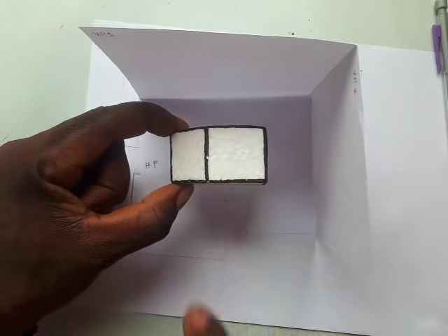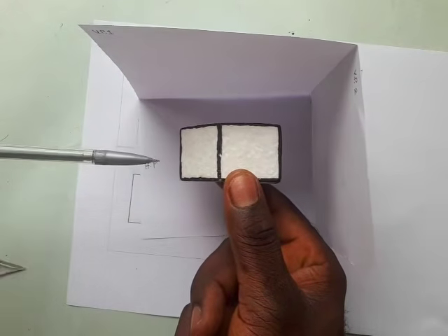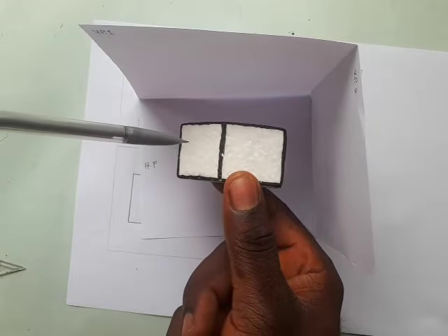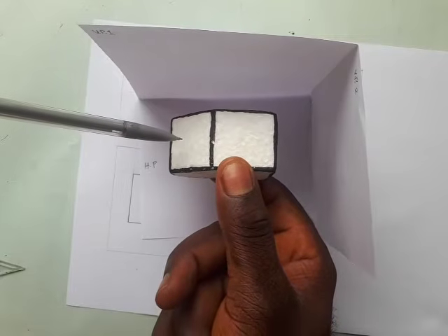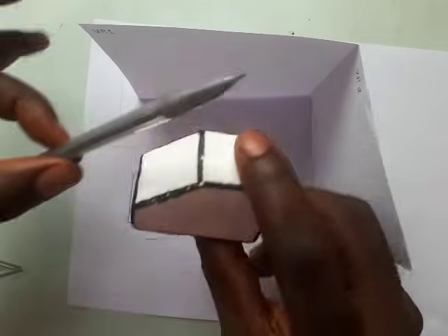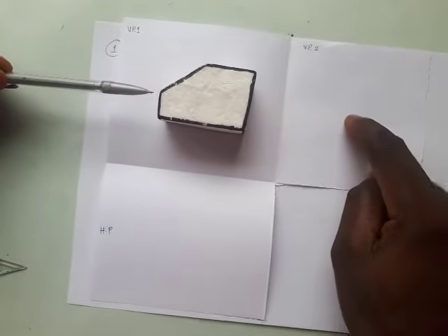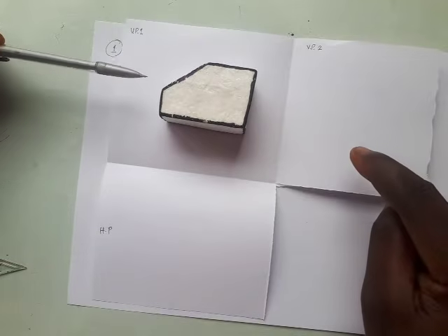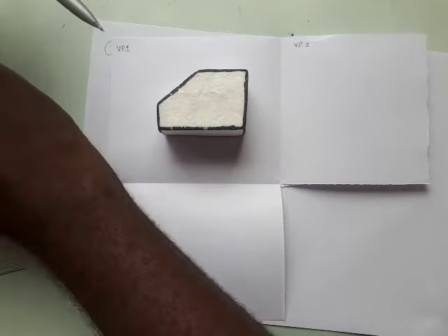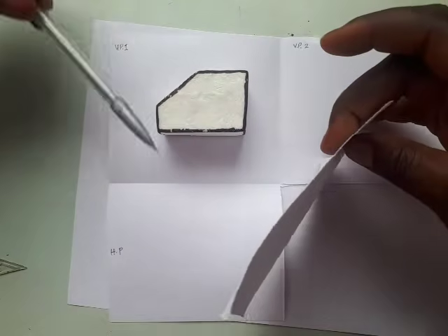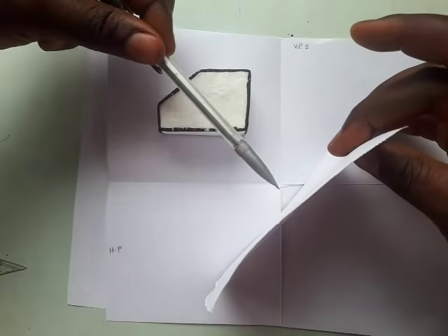It's called plan. Now, if I now move from here, instead of viewing perpendicular to this surface, I decide to move to an angle here, something like this. Now, this becomes what? An auxiliary view. Let me put it in a way that you will understand. I am not viewing like this, perpendicularly, to get my end elevation here. No. Instead, I am moving from this angle and I'm viewing at this angle. So that means I am going to have to create a plane for it here, where I'm going to draw it. And the plane has to be perpendicular to the view. So you see this plane, this is the view, so it's perpendicular.